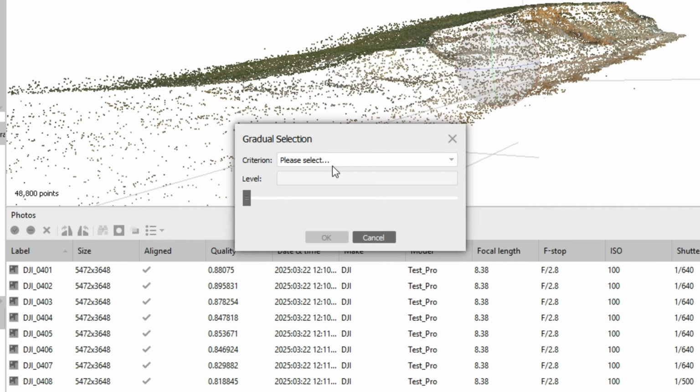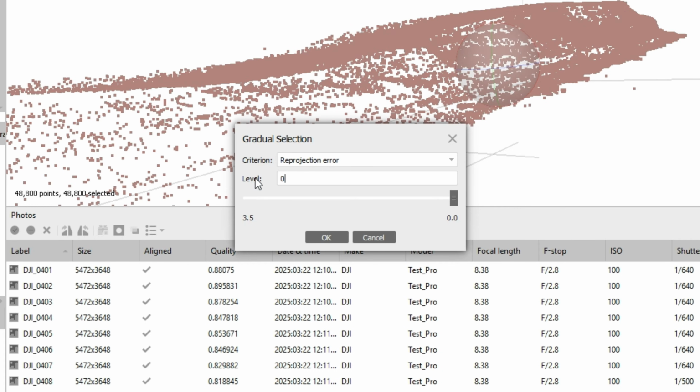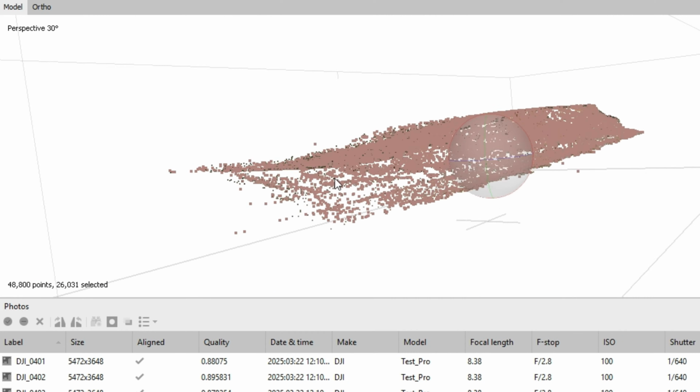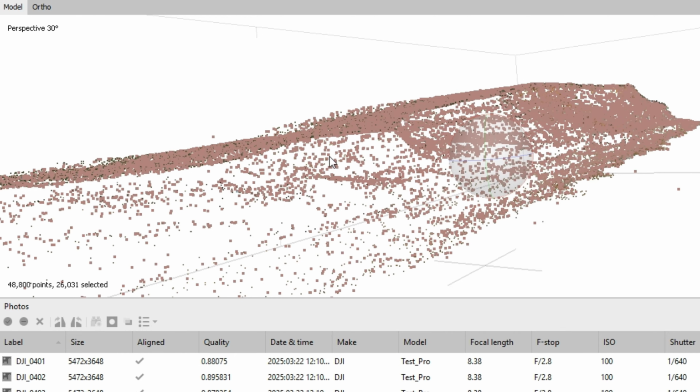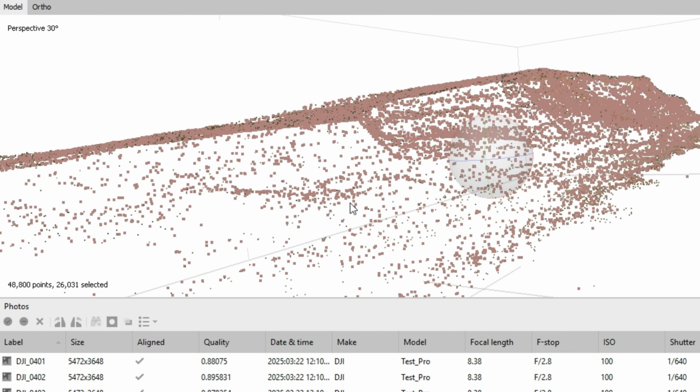And finally we can get to our reprojection error. So we want to have a value. This is also going to make you cringe a bit, but 0.5. So 0.5, quite important. It's a nice low value. It indicates where there might potentially be a few outliers that we don't really need to worry too much about.